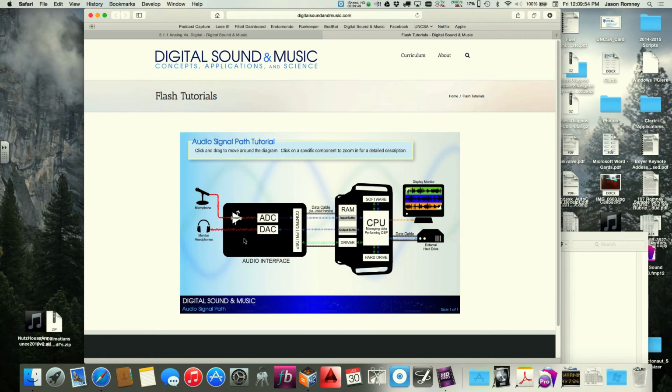They were playing back sound, and it turned out that I came in and looked at it, and what Maria was doing is she had her external FireWire drive, and she was taking it down to the tech table. She was creating all of the audio files and cues, and just plugging her FireWire drive into the Mac up there, and streaming those files off of that FireWire, which normally would be probably okay, but in her case, she was playing a lot of stuff, big, massive, multi-channel audio files, and the FireWire bottleneck was becoming a factor.